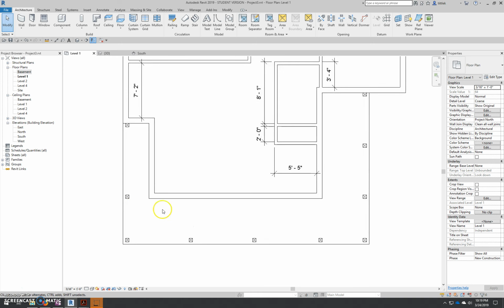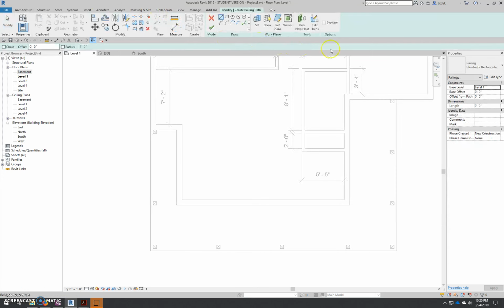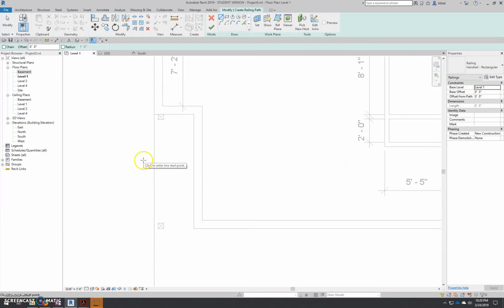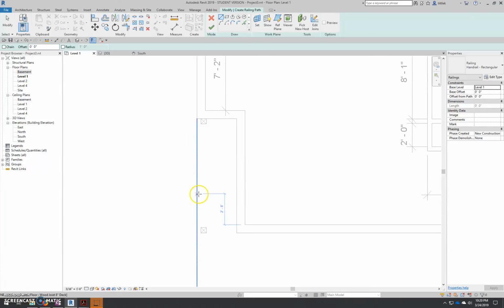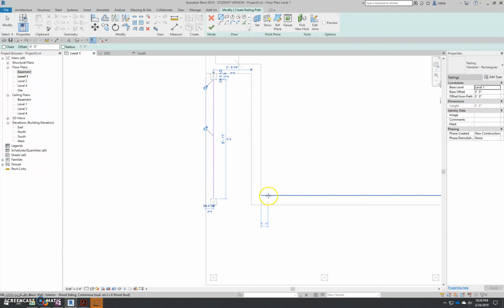I'm going to go ahead and work on some more porch details. We're going to place the railings. So this is going to take a little bit of work. The railing is on the Architecture tab, so I'm going to click Railing. Now, handrail rectangular, that's fine. That's going to work. We're going to start with that at least. And the way that handrails work is that you draw a line representing the center line of the handrail. So basically, I'm just going to click from the midpoint of this column to the midpoint of this column, and that line represents my handrail.